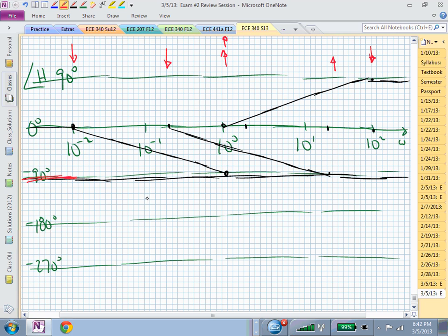Now I'm going down at 45 degrees until I reach 0.2. Then I increase that slope. And so I might say, oh, well, maybe here I'm at some angle, maybe minus 50 beyond minus 90. So I'm maybe at minus 140. Then I say I'm going down 90 degrees per decade. So at 2, I would be 90 degrees lower than what I am here. And I might find that spot here. And I would draw that line until I intersected with 1, and then I go flat.